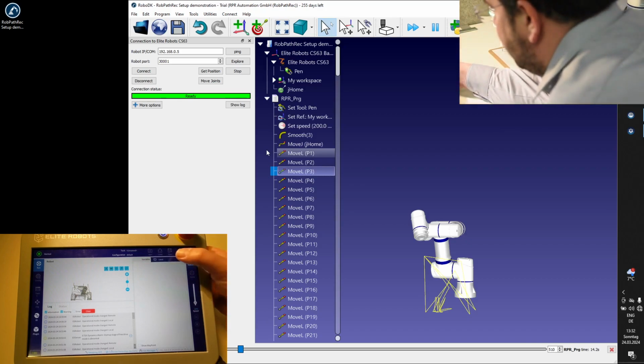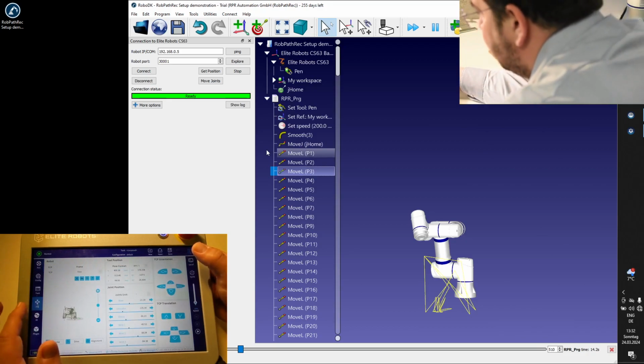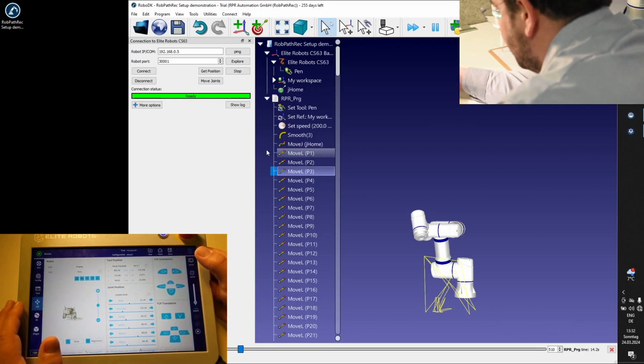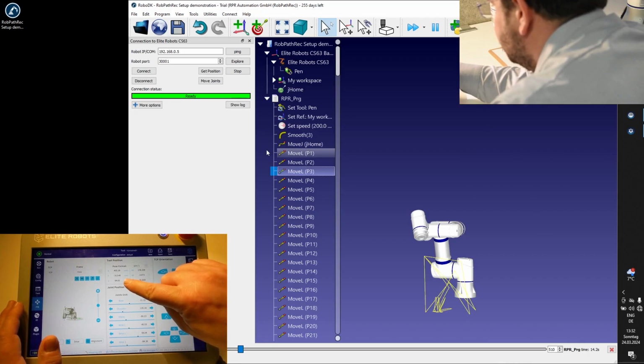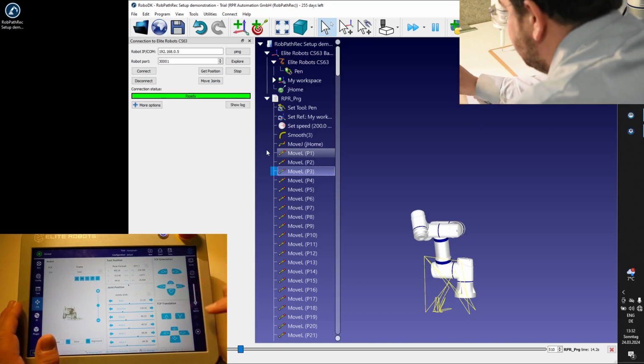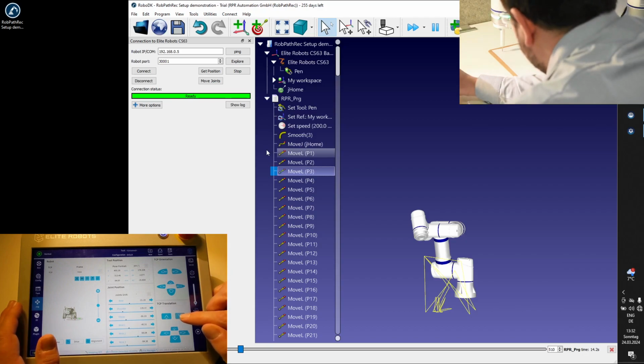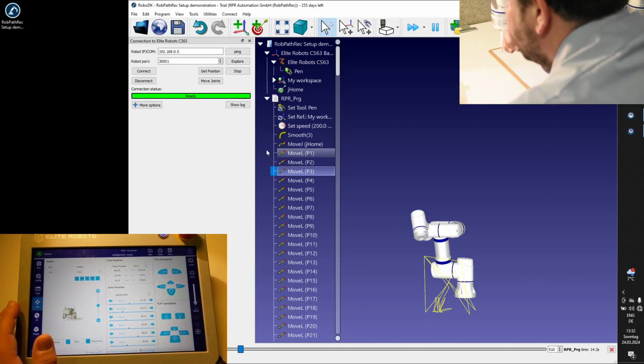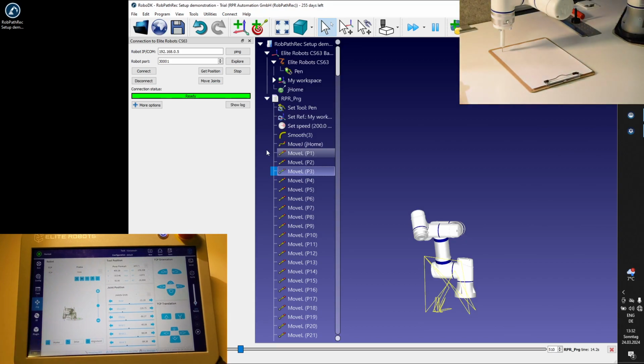So in this case I would really come to the local mode with jog, and here please pay attention to the Z coordinate. So this is 84.66, and with low speed we just hit the paper in a manner that we can make sure that with our pen we can write. So this would be for me approximately 3 mm offset.